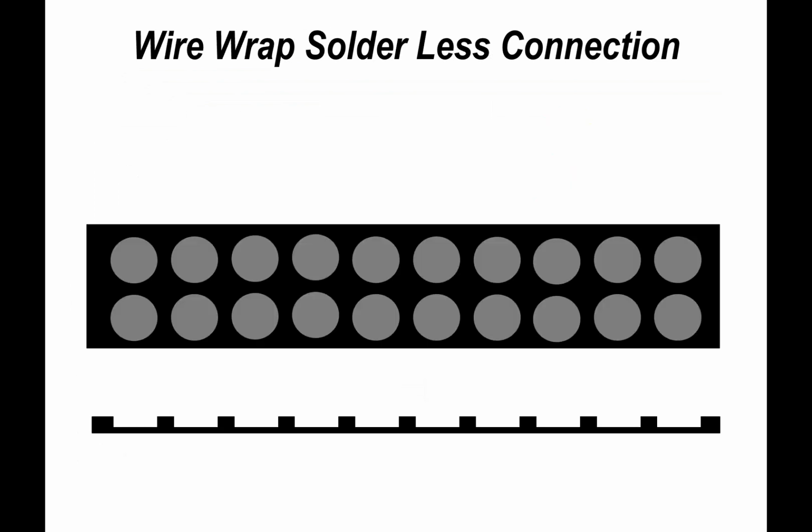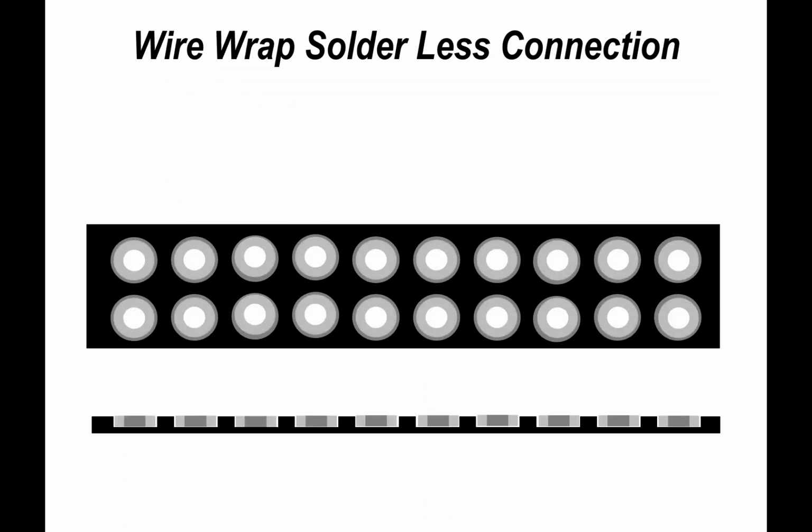So back to the preforms for a moment, because that's what we're talking about today. There are lots of different methods of getting preforms onto connectors. And of course, it comes down to an engineer figuring out the most effective way of doing it. The way in which we started production on our backplane assemblies was having a tooling plate with recesses in, and we would literally sweep the preforms into the recesses as you see here.